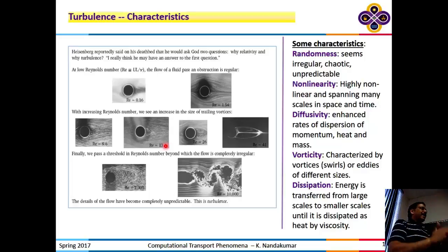Okay? So what would happen if you take the same Taylor-Couette problem that you had, you've crossed the threshold, you've gotten these cellular flows, and you continue to experiment by increasing the Reynolds number, the rotational speed? What do you expect will happen? Fixing the same number of grid points, you will begin to get garbage, right? Because the gradients become very small in reality, and you are not resolving the gradients. So there will be significant errors introduced. In fact, the numerical algorithm would simply blow up. It won't converge.